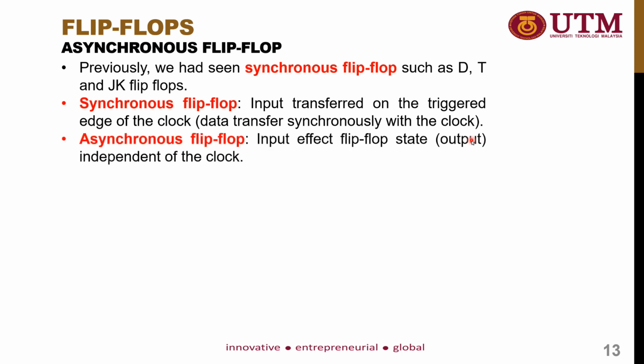In an asynchronous flip-flop, the input affects the flip-flop state independent of the clock. So basically, for an asynchronous flip-flop, the input transfer to the flip-flop doesn't depend on the clock input. It doesn't matter what the clock input is. The output will change immediately if there is the required input to change the output.